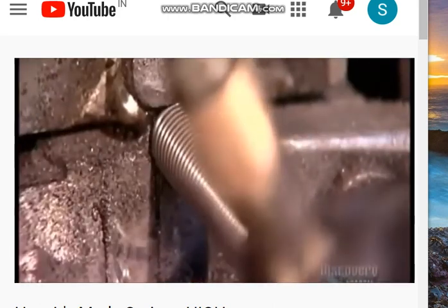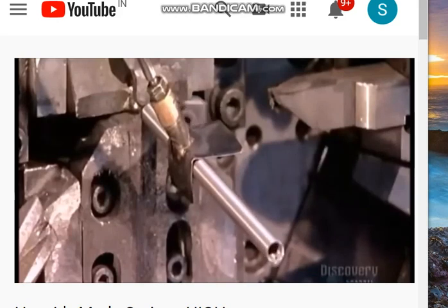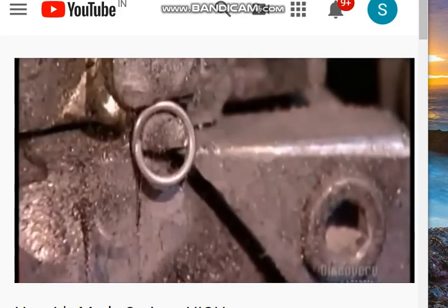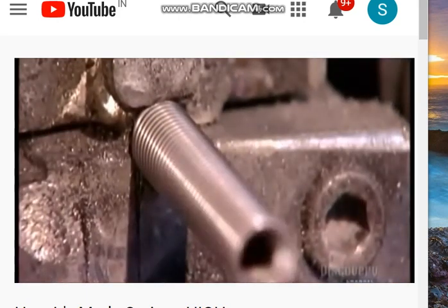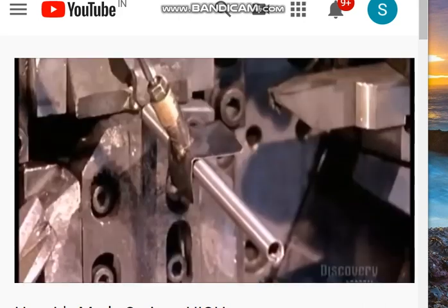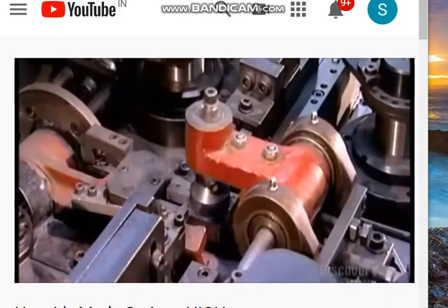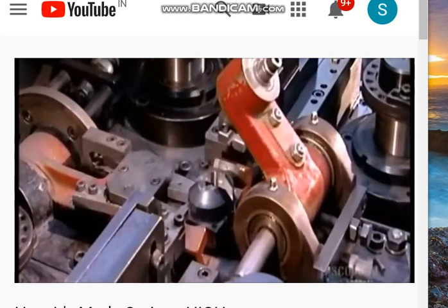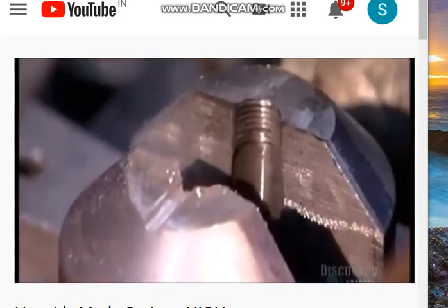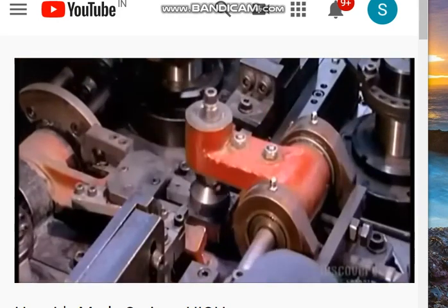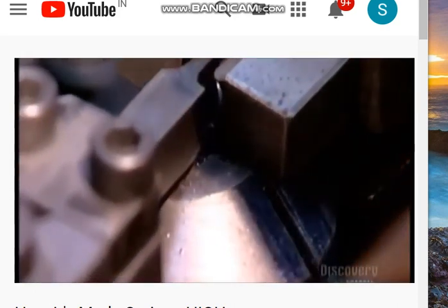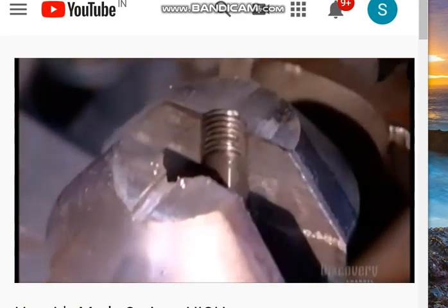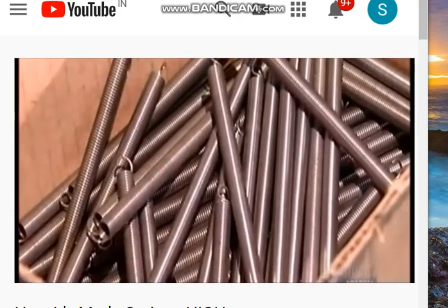You see, this is a helical spring. One wire is being fed, and what you are getting is a helical spring. And this helical spring is a close coiled helical spring. It is used for tension. That's why a ring is also being formed. And you are seeing different methods by which it can be made. So the ring is lifted now. See the top? Yeah, that is for holding. Like that. These springs are all tension springs.